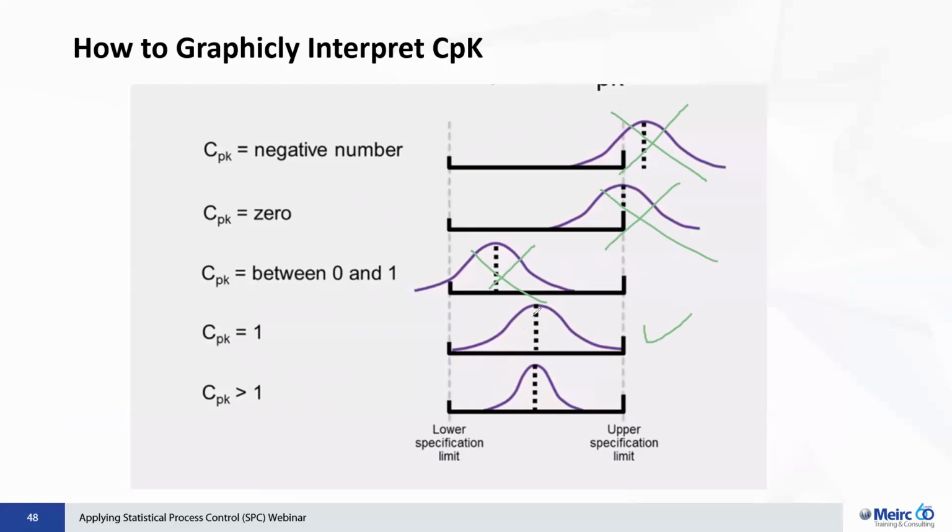As we start to reduce the variation, your CPK becomes higher than 1. The magical number that industry will accept as good is 1.33, right? 1.33 means that the number of defects that are generated are manageable. The number that we are looking at is around 6,000 out of 1,000,000 times you run a process.